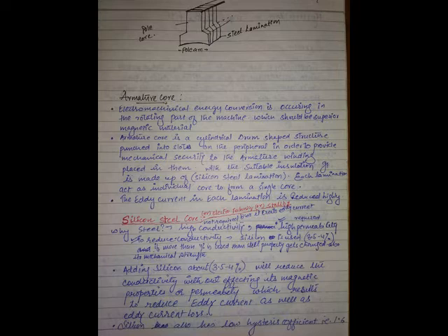Let the machine be running at 1000 rpm or 1500 rpm. This is the speed of rotation, revolutions per minute. We are interested in the number of segments passed by a brush in 1 second. So the peripheral velocity is very, very high. You can expect some 5 or 10 commutator segments passed by a brush in 1 second. Now, if there exists any improper connection between the brush and the commutator, electrical or mechanical, any improper electrical or mechanical characteristic will give rise to sparking.